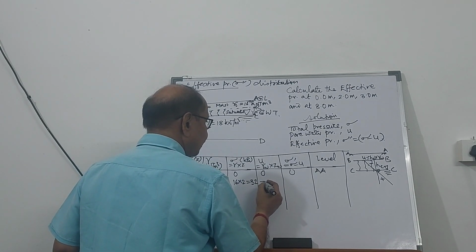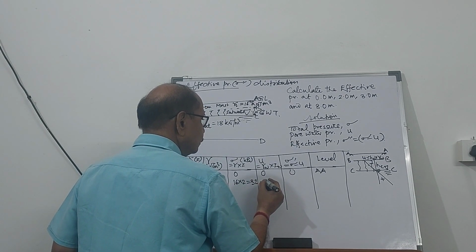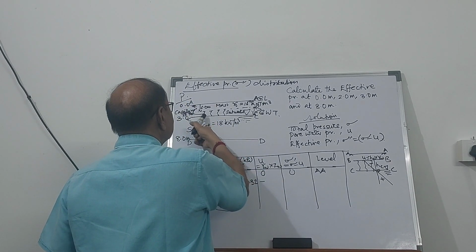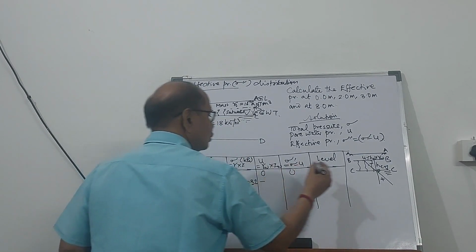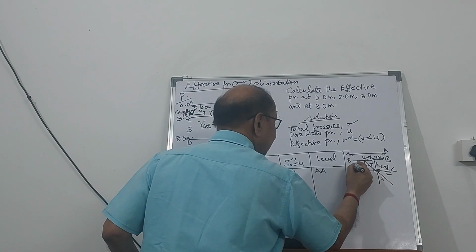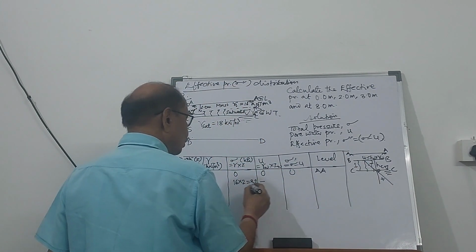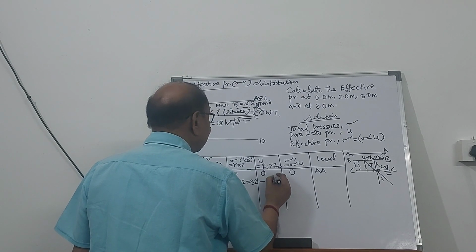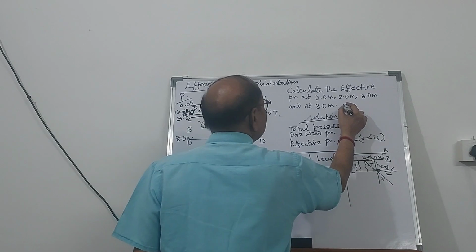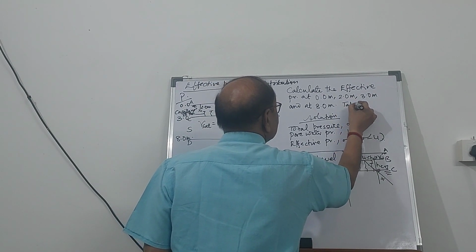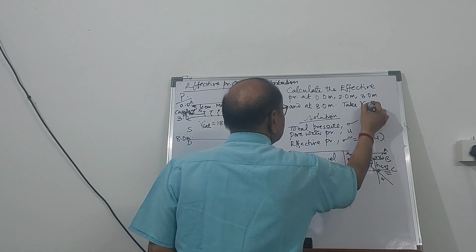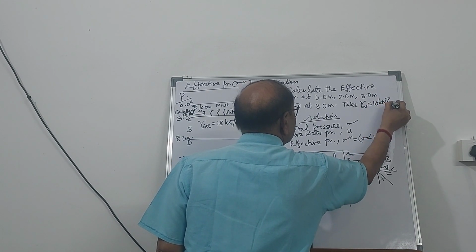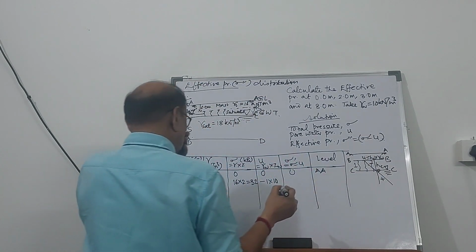It is going to be minus SC, which is 1 meter, as I have given you that this is 2 meter. So this is 2 meter, this is 3 meter. So naturally this is 1 meter. So SC becomes 1. And gamma W can be taken in this problem as the unit weight of water equal to 10 kilonewton per meter cube.